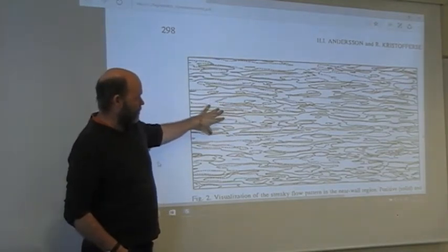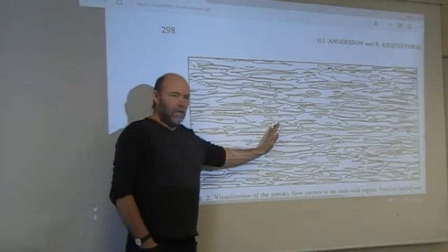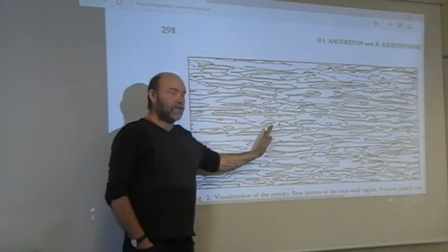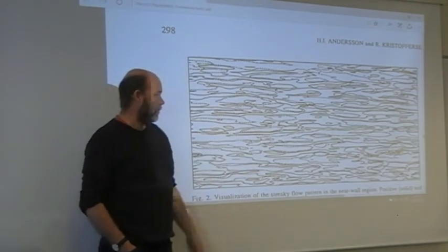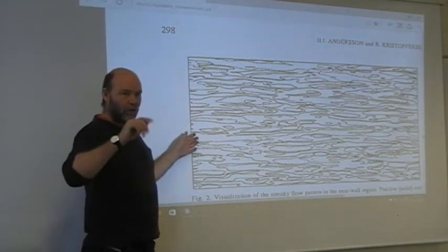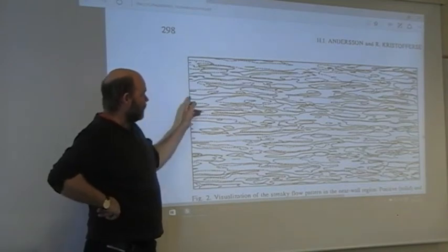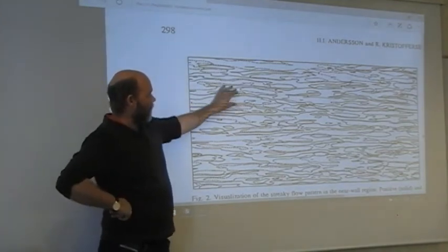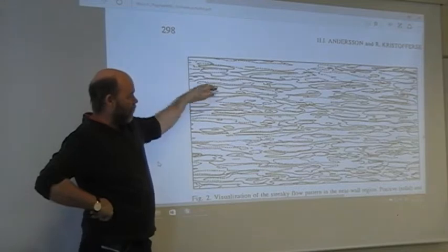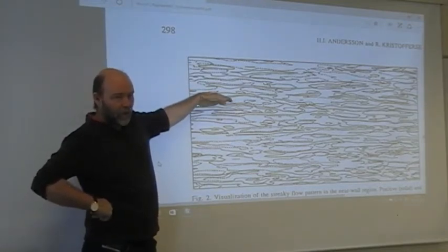And what you see is just a contour plot, isoplot of the streamwise velocity, but the average is subtracted. So here it is just the u-fluctuation alone that you are watching. And the solid lines, meaning you have a region where you have a positive u-fluctuation, the velocity is fast.